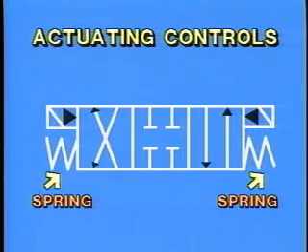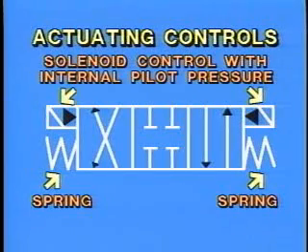To show that a valve is spring-centered, a spring symbol is placed at each end of the envelope. This schematic shows that an electric solenoid and pilot pressure assist are required to overcome spring force to move the valve spool.